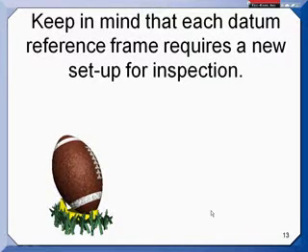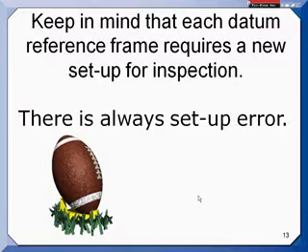Keep in mind, when you keep adding datum features, there's always setup error. I set the part up to measure it, I take it away, I bring it back, it won't end up exactly where I put it. There's always those little bits of setup error that can throw things off and give you different results.